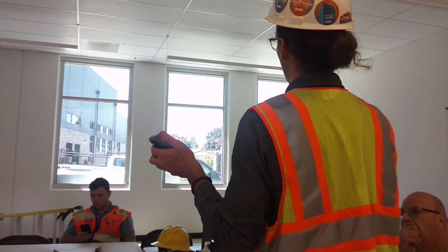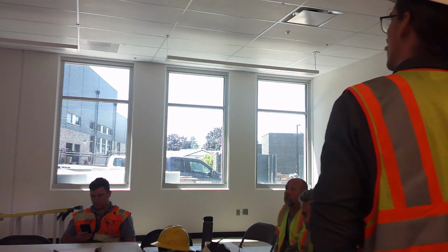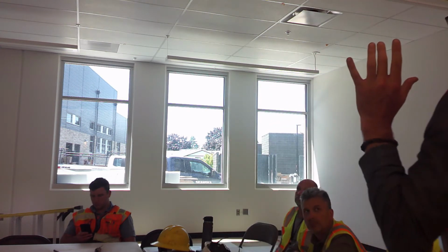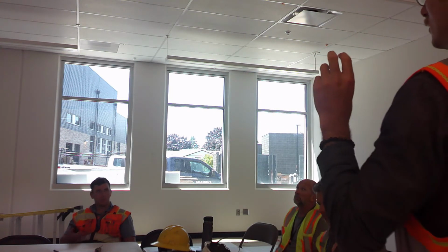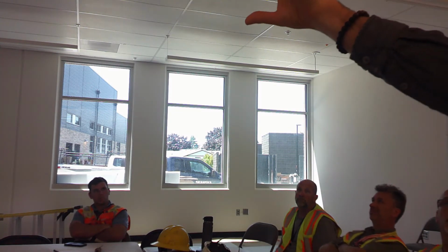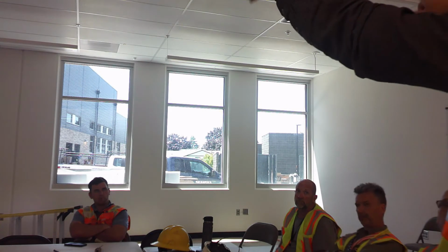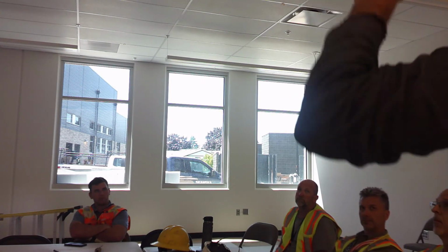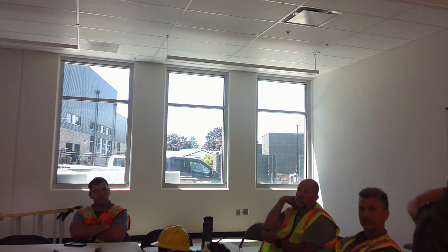So let's talk about the typical setup of all the classrooms. You've got 6 individual zones. You've got 2 switch legs, if you will, so your A and B, but then those are divided up into daylight zone 1, daylight zone 2, non-daylight zone. So 6 individual control legs.